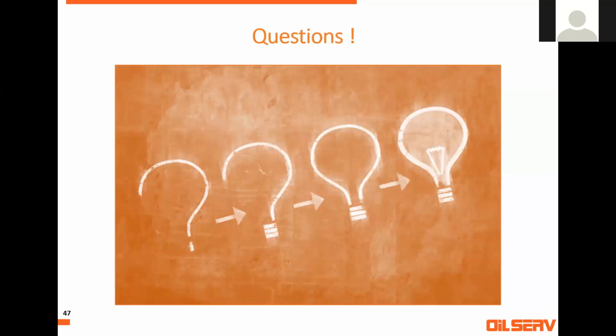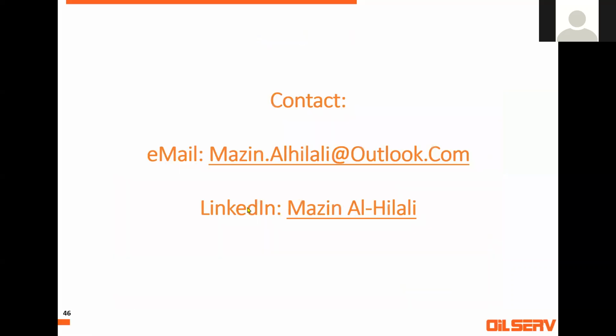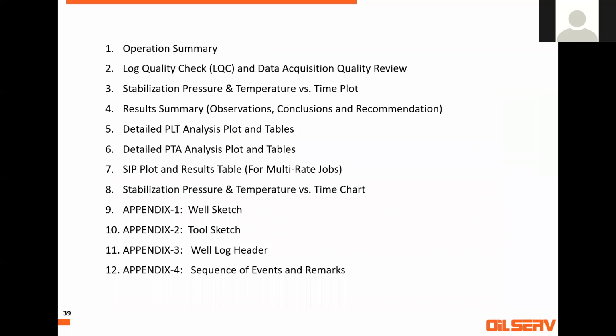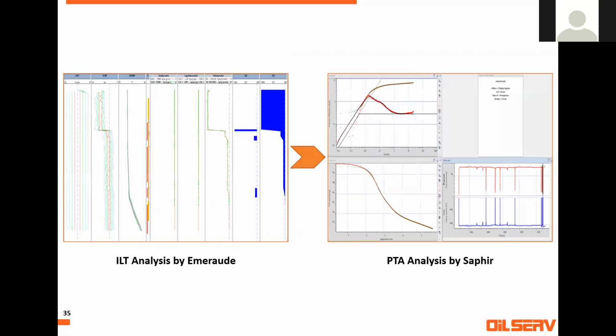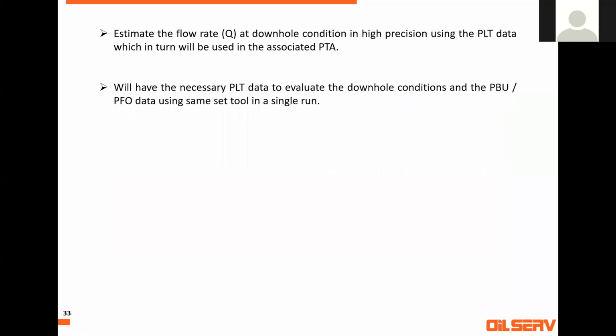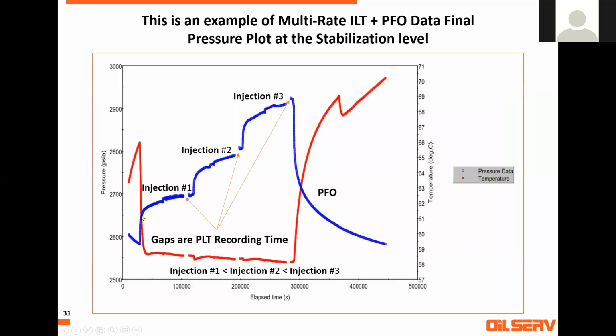Okay, and have you done any temperature well test? Temperature well testing, I get your point. I saw one of them logging the temperature. You see this red curve? This is the temperature. Usually when they make this stabilization plot, they keep the temperature log recording.